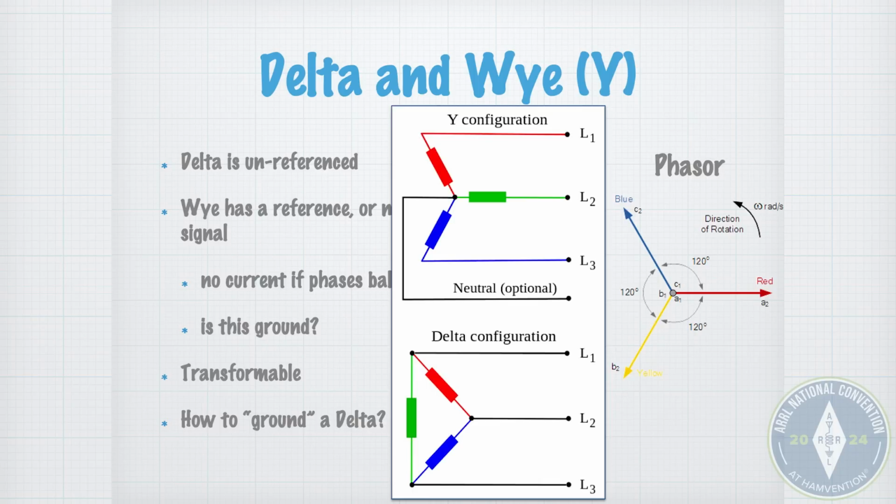But there's a transformation that will take you from the Y configuration to the delta configuration. It's completely equivalent, completely algebraically equivalent. So you can just crunch through this and you'll get the changes in voltage and current. And then when you get to delta, where's neutral? It's gone. So the neutral is kind of an overspecification of the situation. But now you don't have a reference anymore.